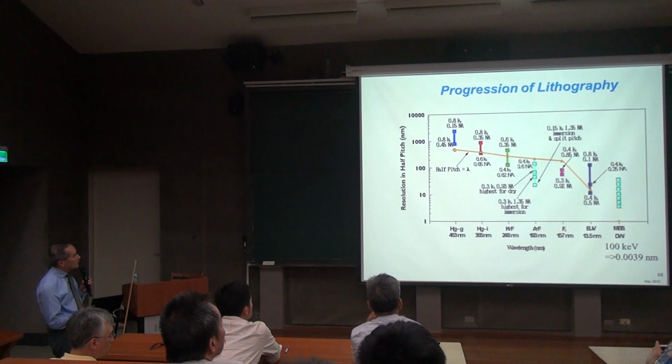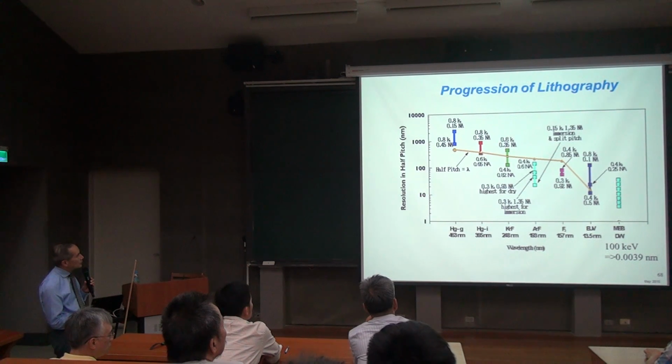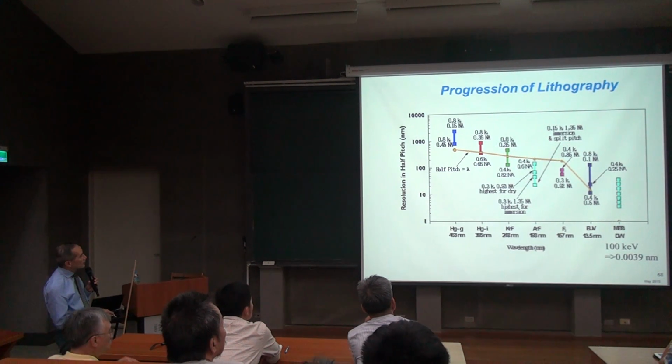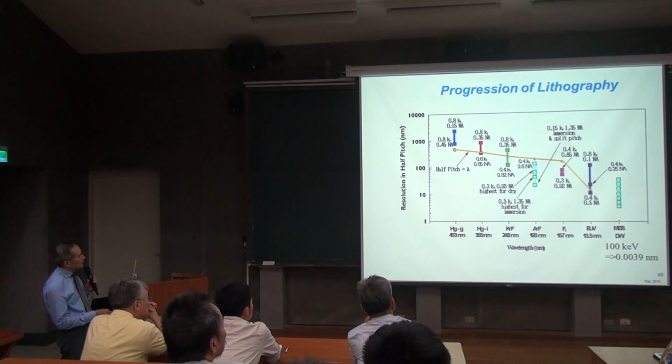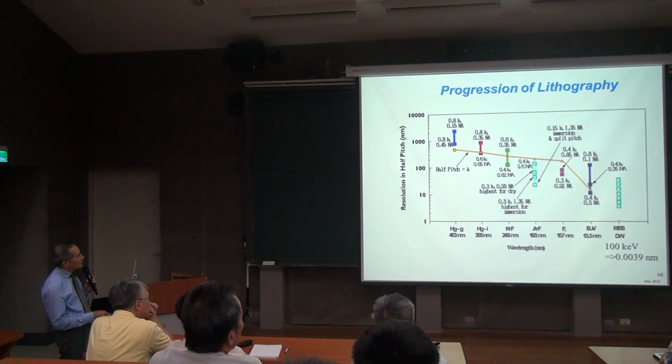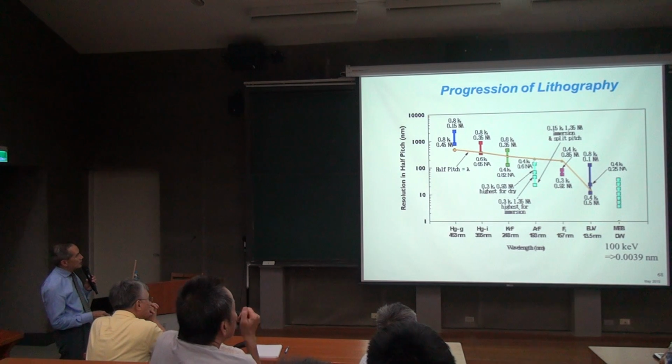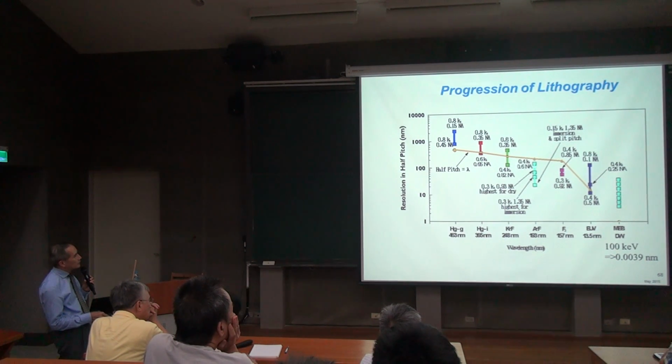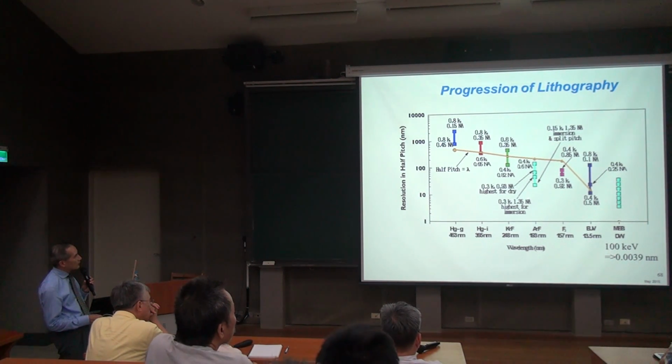Then we keep on going. Well, actually, this is my wavelength line. And this, we're pushing I-line lithography a little bit lower than the wavelength. And at 248, we stay at 0.6 K1, and then we relax the NA to 0.35. We gain depth of focus that way. And then we keep on pushing it until we reach 0.82 NA and 0.4 K1, and it's way below wavelengths. In argon fluoride, we cannot allow anything even equal to wavelengths. Everything was sub-wavelength. And with argon fluoride, we push all the way to NA equal to 1.35 and 0.3 K1.